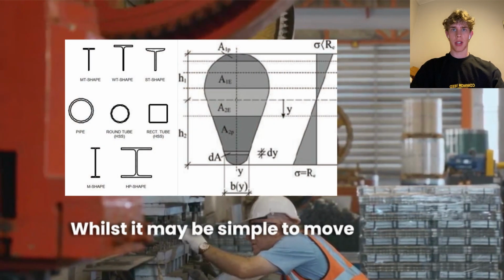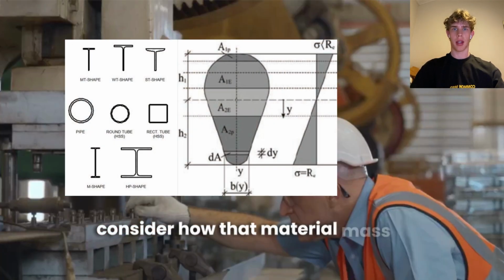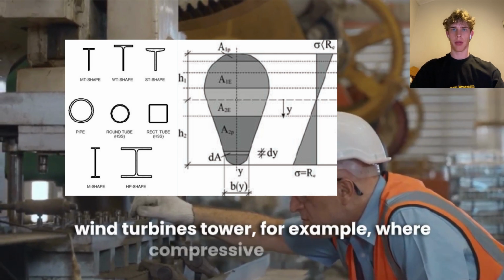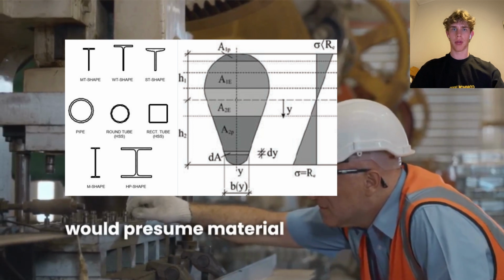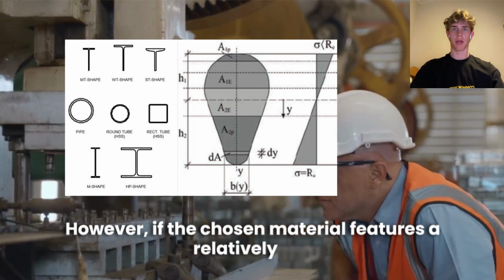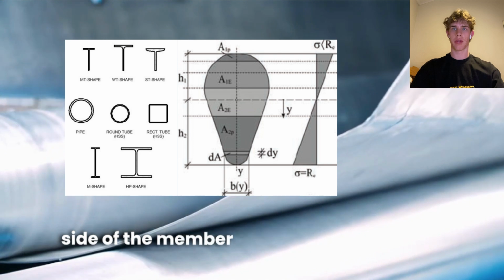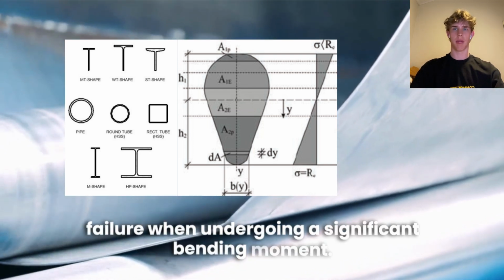Whilst it may be simple to move material away from the neutral axis, it is also important to consider how that material mass is distributed. With the wind turbine's tower, for example, where compressive forces are largest, it would be safe to say that most would presume material needs to move to the compressive side of the neutral axis. However, if the chosen material features a relatively low tensile strength, reducing the cross-sectional area of the side of the member in tension may result in failure when undergoing a significant bending moment.